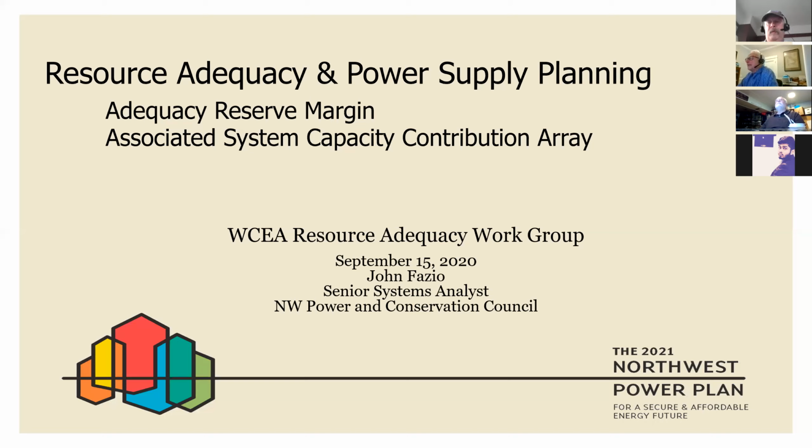how they work together. I should mention, since Fred brought it up earlier, that there really is a substantive difference between what I would call short-term and long-term adequacy. They are obviously related, but what happened in California and what could happen in the Northwest is, as I would describe it, short-term adequacy: managing existing resources and managing the sharing of information and resources across balancing authorities to try to maintain your operating reserve requirements so that you have a stable system and you don't cut anybody off.